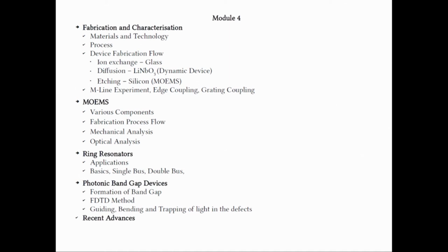One experiment we have discussed on the measurements, the planar waveguide measurement, is very important to characterize the process, where we can estimate the refractive index profile, then the losses and many other factors of the planar waveguides. So, when it comes to the channel waveguide, we can couple it by using edge coupling through a fiber, and also more recently one of the most popular techniques to couple light into the optical circuits is by grating couplers.